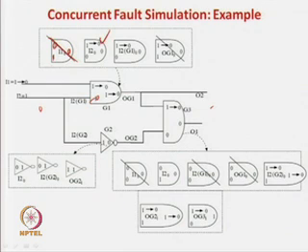So, what we are doing was a very simple thing, we are going for event driven simulation. So, we are just changing whatever signal is required, this is a change here, this is a change here, and in this case after doing this change, you can find out here is that this gate and this gate remain similar. So, you can drop it, but for the second case there is I2 stuck at 0 fault, there is a signal change from here, this does not change, this remains same.